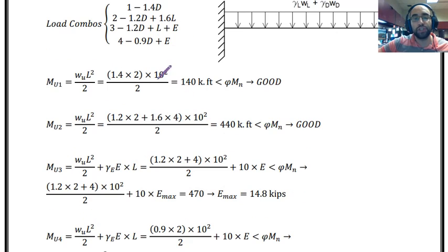So far we were just checking the strength of the section because of gravity loads, and they all pass. If phi Mn was smaller than these, we should say the section is already failing under gravity loads and it has no capacity for earthquake load. So maximum earthquake load is equal to 0 because the section has already failed under gravity loads.